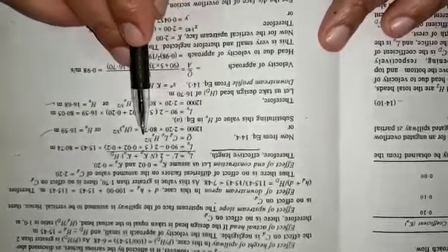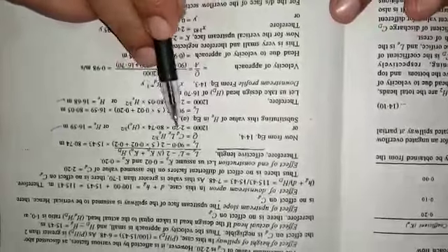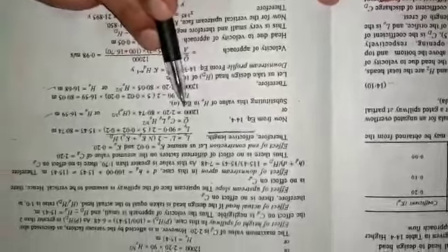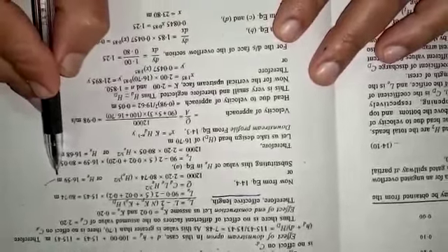Again, using the formula for the discharge and putting the new value of LE in this equation, which is 80.74 meters, and using CD equal to 2.2, the discharge as given 12,000 cumecs, calculate the new value of HE, which comes out to be 16.59 meters.